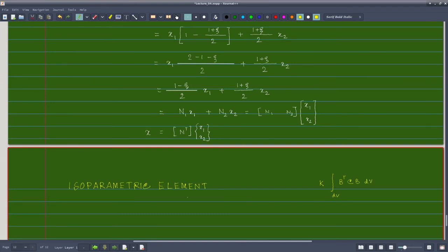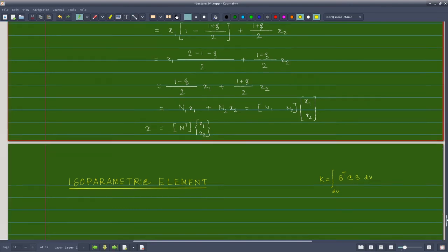Now when I have isoparametric elements, these integrations become numerically easier, so computational cost will be less. Also, the same transformation matrix I need to store only once, so it will save memory also. So that's why an isoparametric element is a very commonly preferred way of defining elements. That's why we have taken up in this case an isoparametric element.